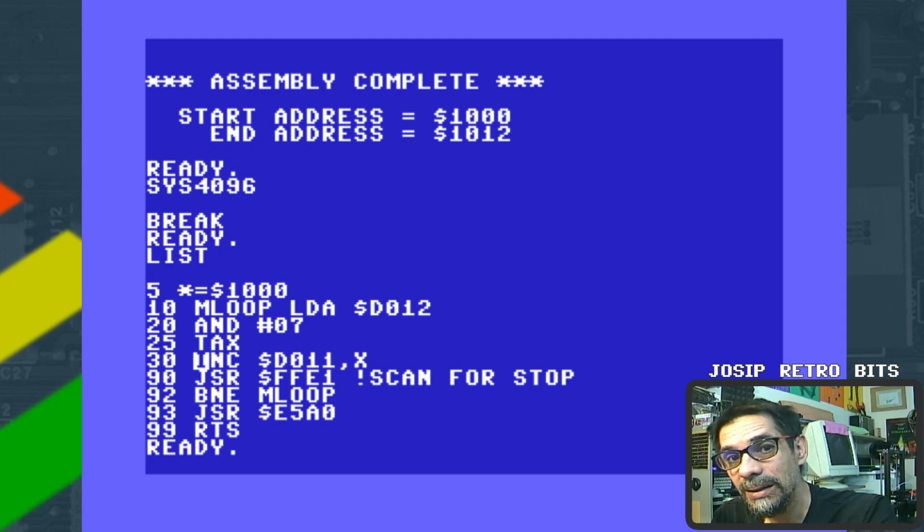Now on this line 30, we had before, maybe in the first example, I explained this, increment the value that's stored in the memory address by 1. It's the same like before, except we use the X register here as well. Now this value in the X register is used as an index or offset if you prefer.